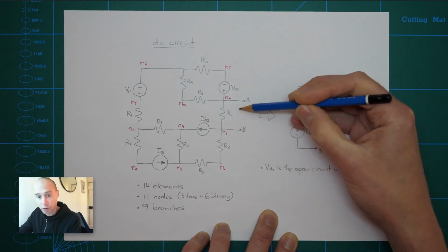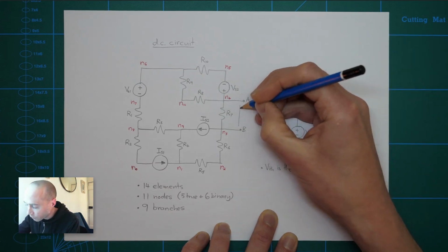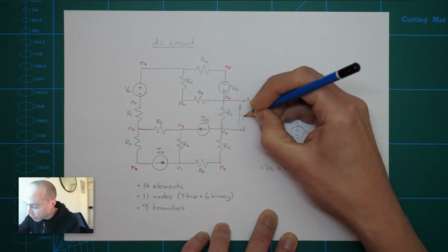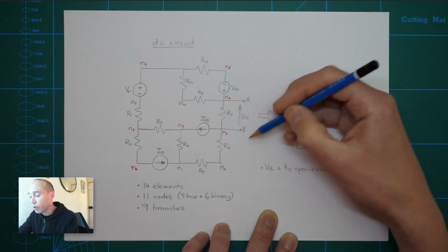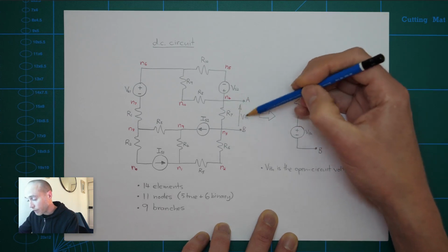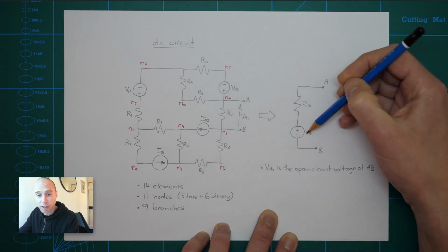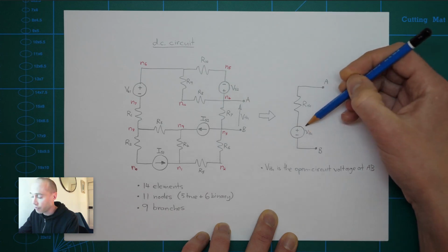So it's this voltage here when A and B aren't connected to anything. I'll label that in here, VTH. If we don't connect A and B to anything, they're just left open circuit. And if we were able to measure the voltage between these 2 points, that's the value that VTH needs to have.